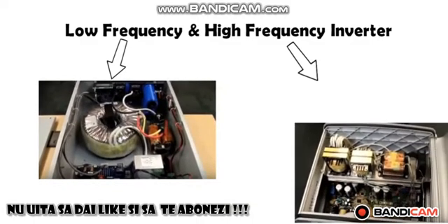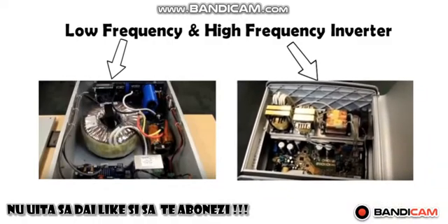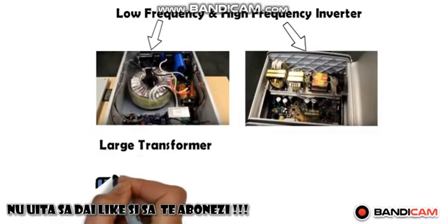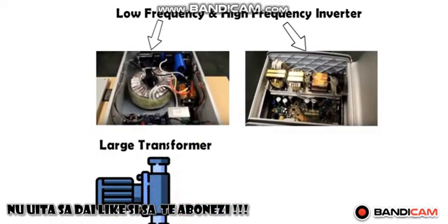A low frequency inverter has several advantages, but it is more expensive, and because of the presence of a massive iron core in its transformer, it is also much bigger and heavier compared to its high frequency counterpart. Often difficult loads that require a high surge at the beginning, such as motors, compressors or pumps, are very well managed by a low frequency inverter.